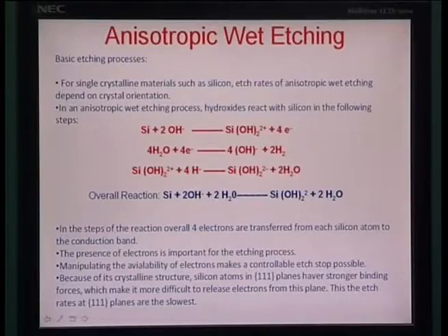Essentially, this is the technique wherein a certain hydroxide based chemical process is used for etching of silicon. So, in this particular anisotropic etching process, the only difference is that the etchant solution is a hydroxide based solution, and therefore, the process is really based on an electron transfer redox reaction which happens between silicon and the particular hydroxide etchant.